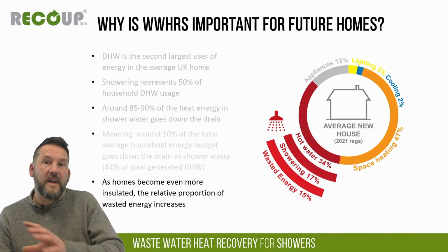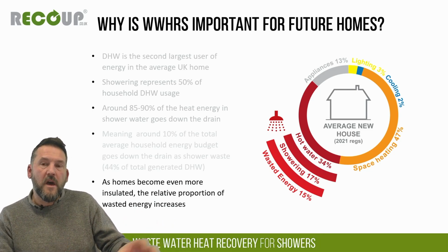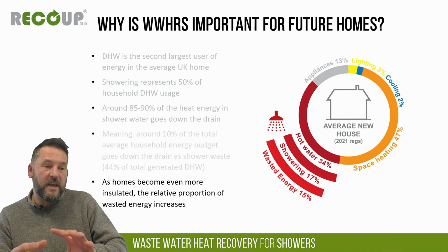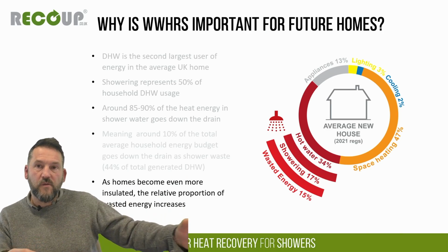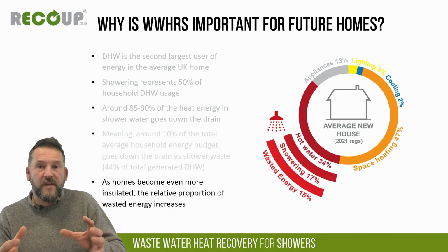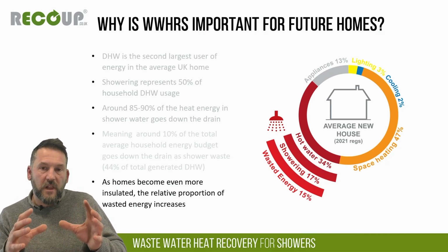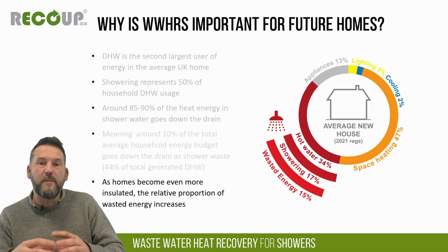And then when we look at the direction of travel that building regs are going, to take it to the end degree with Passive House, where you could be at 10 or 15% space heating versus everything else being hot water, the percentage impact of wastewater heat recovery becomes more significant.